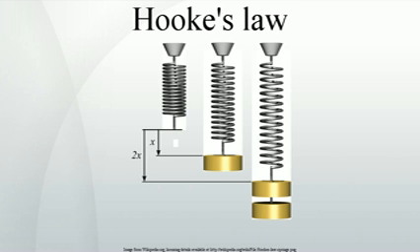Matrix representation of the stiffness tensor. It is often useful to express the anisotropic form of Hooke's law in matrix notation, also called Voigt notation. To do this we take advantage of the symmetry of the stress and strain tensors and express them as six-dimensional vectors in an orthonormal coordinate system as. Then the stiffness tensor can be expressed as, and Hooke's law is written as. Similarly, the compliance tensor can be written as.